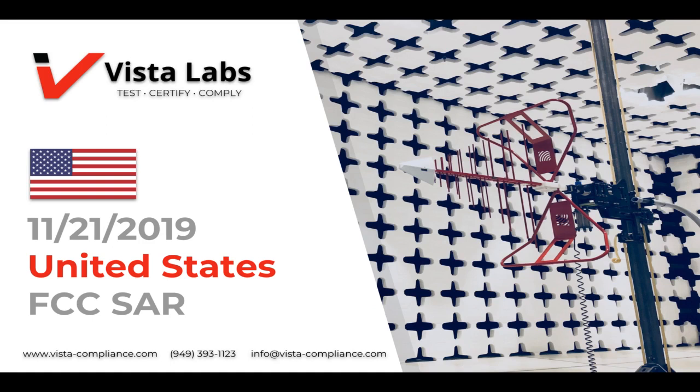Every electronic and wireless product needs to go through wireless testing and certification. Part of that is RF exposure evaluation. So that's the impact that this product has on the environment and the human body. So today we'll be talking about the requirements set forth by FCC regarding RF exposure, specifically working our way to SAR, which is specific absorption rate for products that are used in close proximity with the human body.